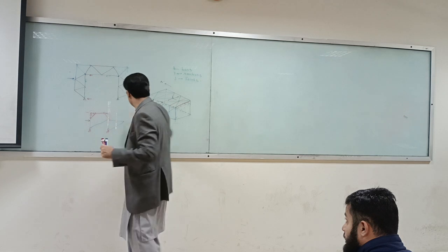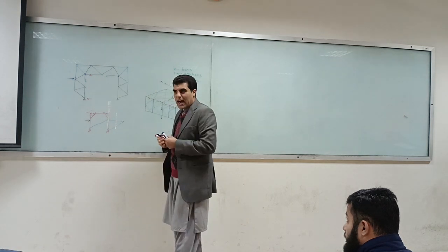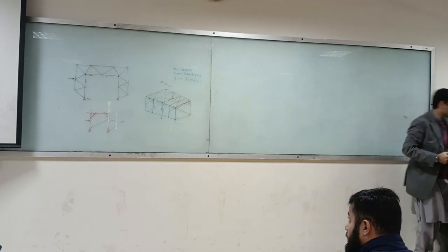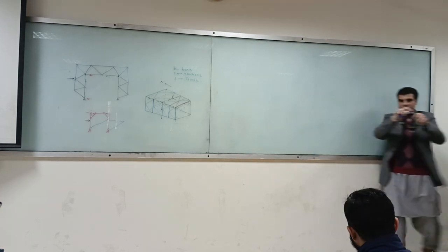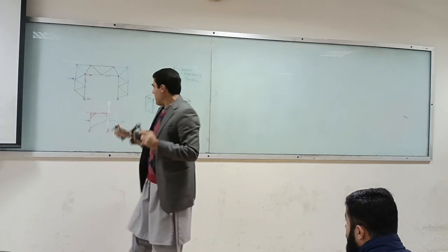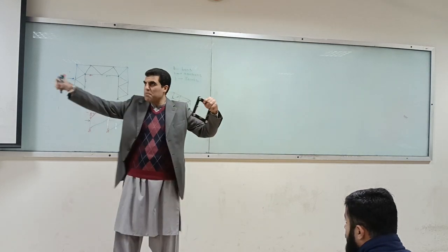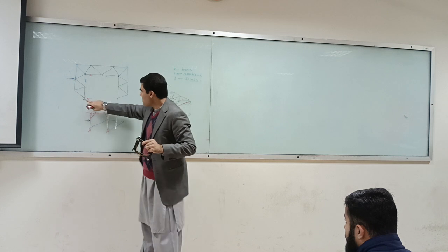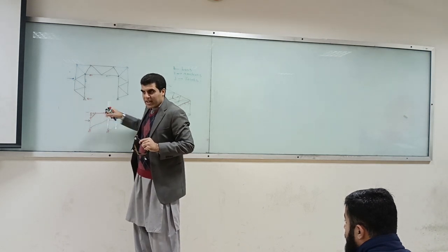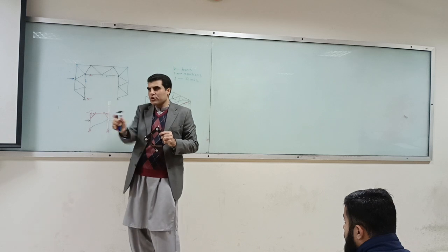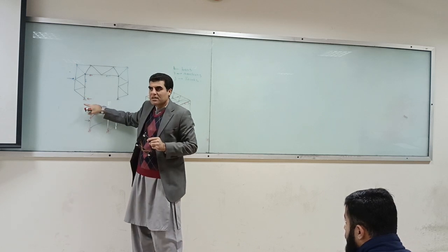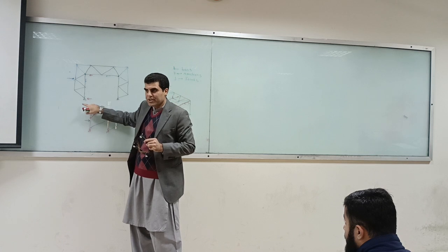In the truss structure, you have pins which are connected. So this thing is internal. By external, I mean that you have a support. So this will be placed, there would be a foundation over here. That foundation can rotate. So that's why I have made it a hinge.